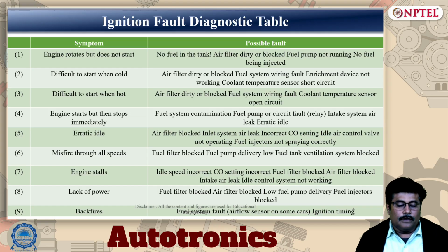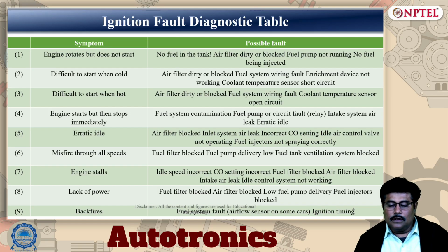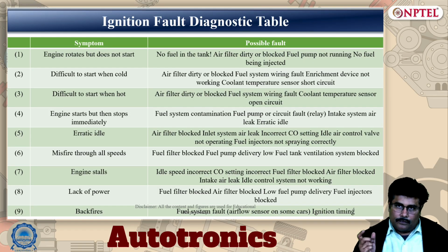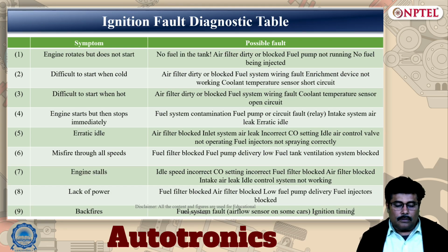Sometimes it is difficult to start when cold: a dirty or blocked air filter, fuel system wiring fault, enrichment device not working, and coolant temperature sensor short circuit. Sometimes it is difficult to start when hot: a dirty or blocked air filter, a fuel system wiring fault, or the coolant temperature sensor having an open circuit.